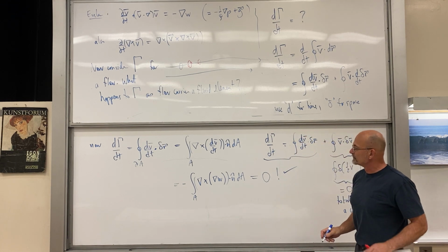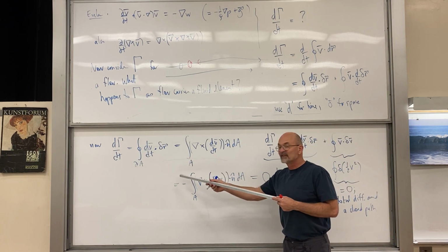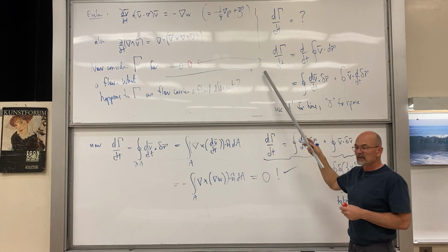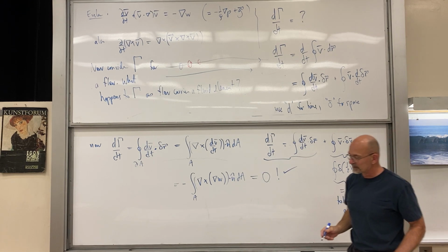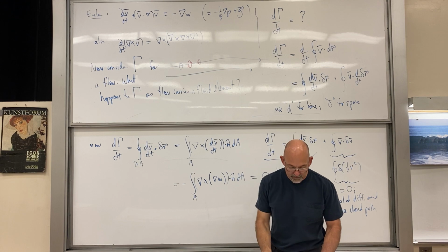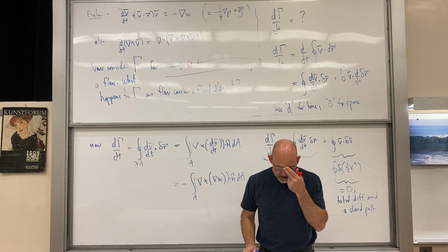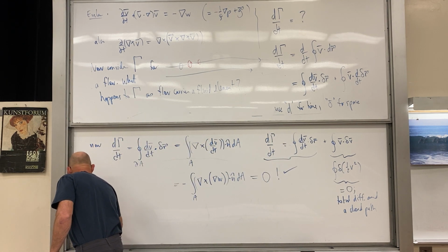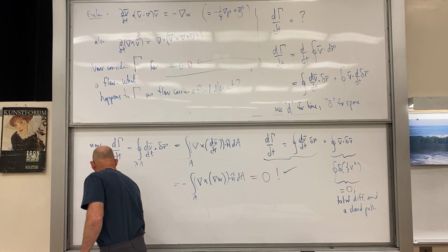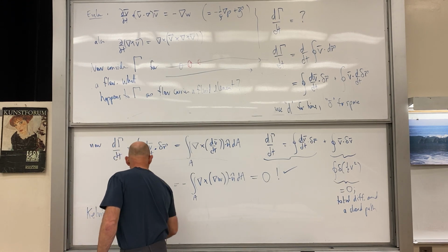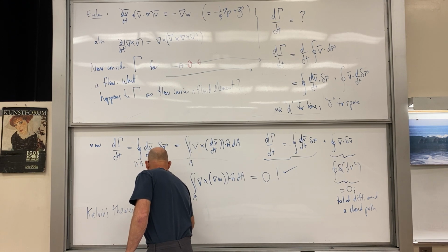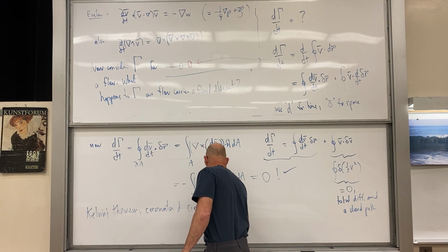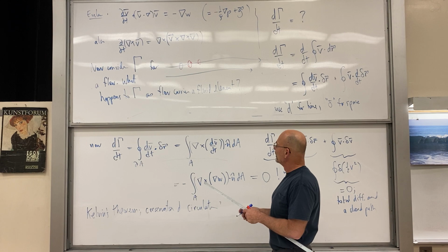Exclamation. Okay. So apparently the circulation remains constant as water is carried along streamlines. Okay, circulation remains constant, and this is called Kelvin's theorem, conservation of circulation. So yeah, that's what we wanted. So Kelvin's theorem, conservation of circulation. And again, that line integral is constant.